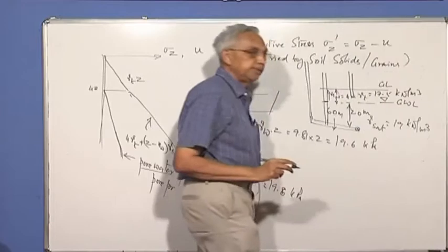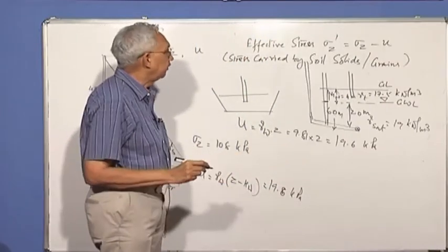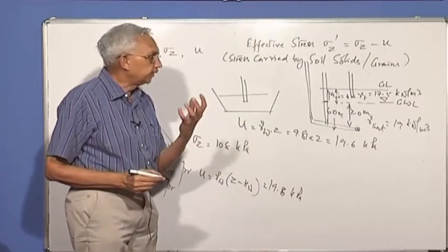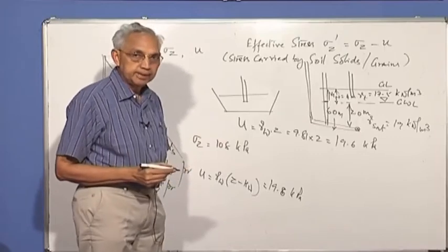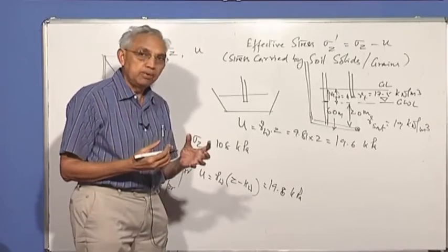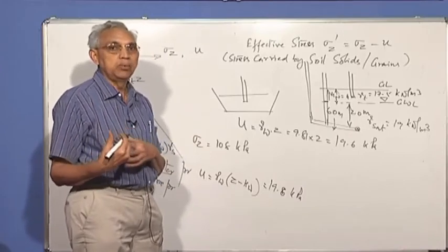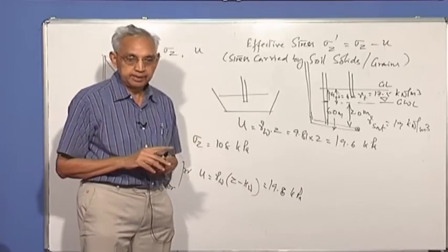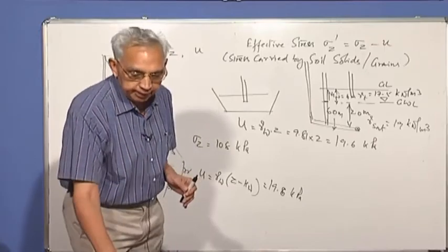This is one of the most important concepts. Effective stress is the stress carried by soil grains. Soil grains don't carry all the vertical stress. The water within the pores will carry part of it. This can be calculated easily.